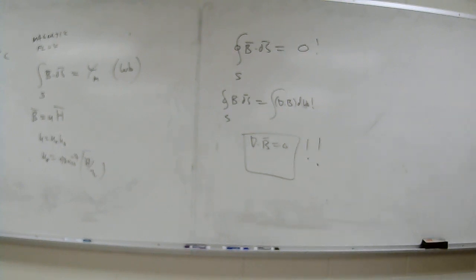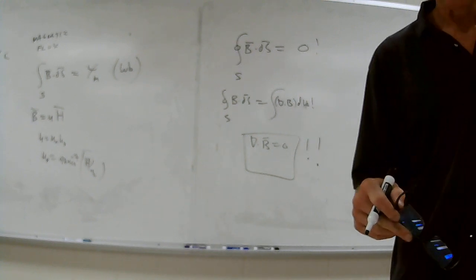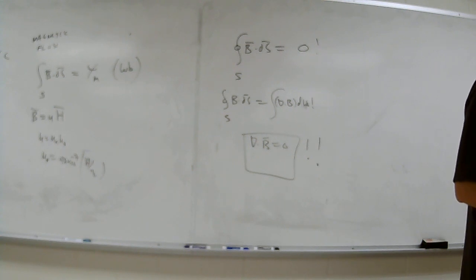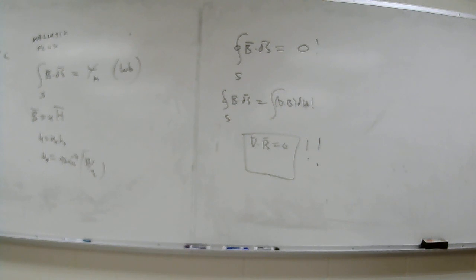Now, in his book, if you have the book, look at page 239 for a second. At the bottom, I want to contrast this one thing. You see how he has the integral form, and then the differential form of the laws. Gauss's law first: integral of D dot dS is Q enclosed, differential div D is rho v. Second one, integral of B dot dS is 0. That's the actual flux. It means divergence of B is 0. Then integral of E dot dl over a closed loop is 0, which means curl of E is 0.